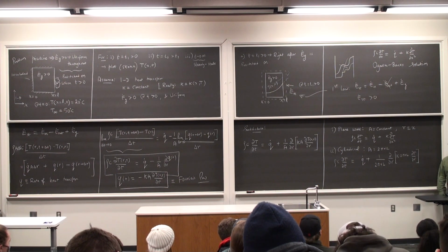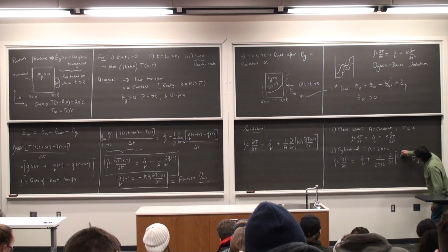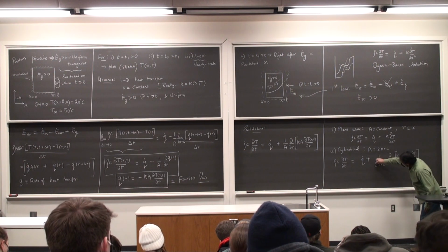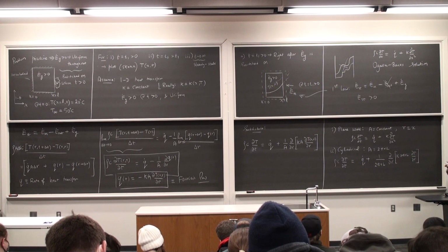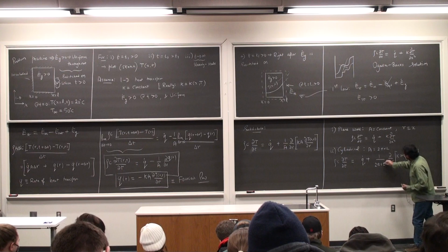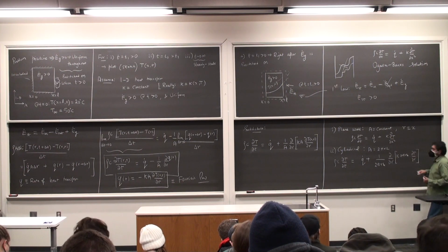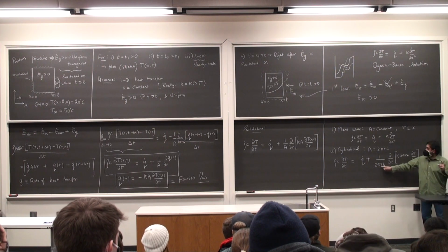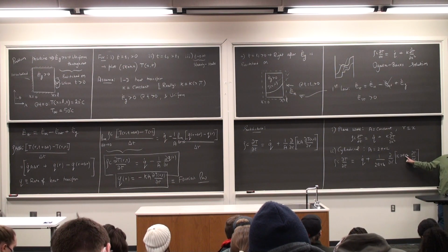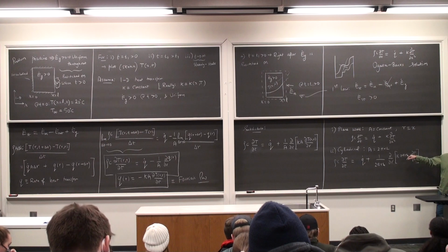So far so good. The 2 pi cancels on both sides, they are physical constants. The length of the cylinder is also a physical dimension that does not change as the cylinder undergoes heat transfer. But I cannot cancel off the r here and the r there, because this is within the derivative.